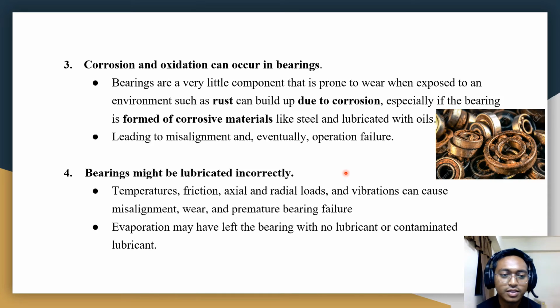My last point is bearings might be lubricated incorrectly. Incorrect lubricant grade, type, or specification will lead to misalignment, wear, and premature bearing failure. Even worse, evaporation may have left the bearing with no lubricant, or with contaminated lubricant.